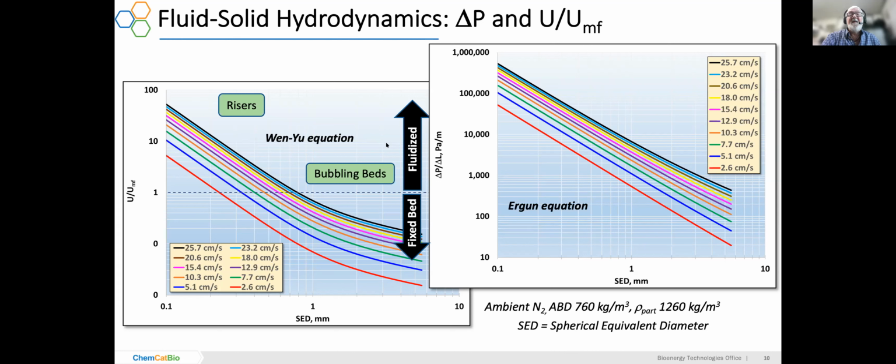And of course, as the particle size gets smaller, the pressure drop goes up because the voids between the particles are becoming much, much smaller, and the viscous drag is increasing dramatically in this case. Now, these can indeed have velocities that are well above UMF, but they can still be fixed bed applications because, for one thing, they could be downflow, and then you don't have any fluidization, or you could simply constrain the catalyst by locking it into the fixed bed by the vessel itself.